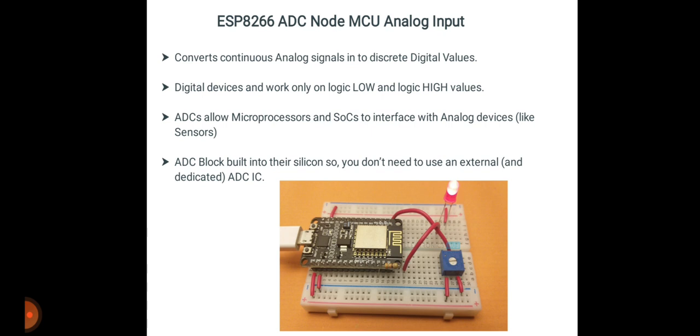First of all, in this tutorial we will learn how to use the ADC peripheral of the ESP8266 SoC and read some analog values. Also, for the demonstration of the ESP8266 ADC pin, we will use the NodeMCU board, which is based on the ESP12E module. Also, the ESP01 doesn't have an ADC pin, we know that. That's why we are using the ESP12E module.